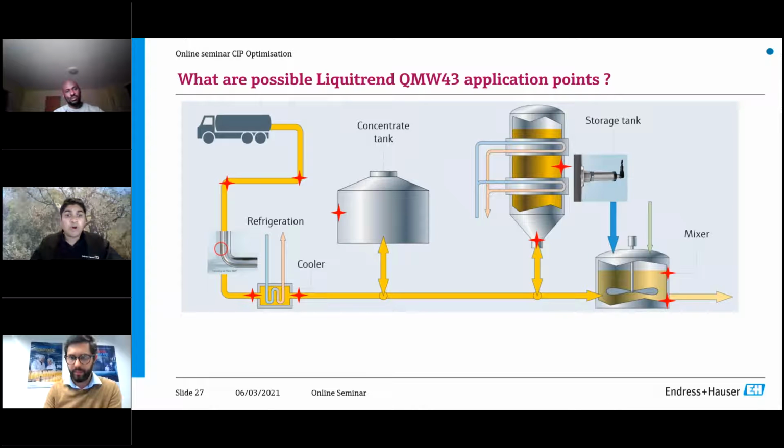Another would be on corners and bends. If you see in this example where the truck is, you wouldn't install the build-up sensor on a straight line, because this naturally is where cleaning does occur. Where cleaning doesn't naturally occur is on corners and bends, because the welding is slightly different over here. You get pivoting or pitting in the welding, so microorganisms can build up over here. So this is where you'd want to measure as well.